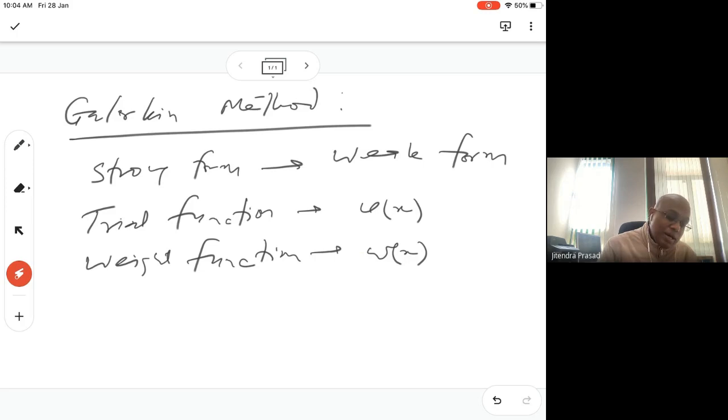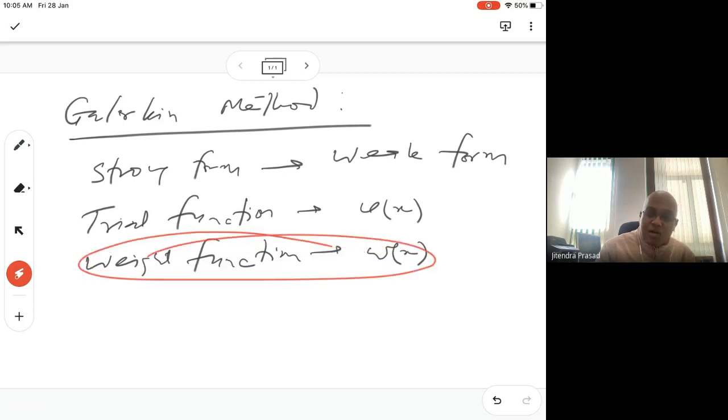Based on that, we do the mathematical analysis, meaning that whatever we have in the weak form, we put this trial function there, we put the weight function there, then we say that the weight function could be arbitrary, so any coefficient cannot be equal to 0, and this cancels out, meaning that we take the weight functions out of the equations.